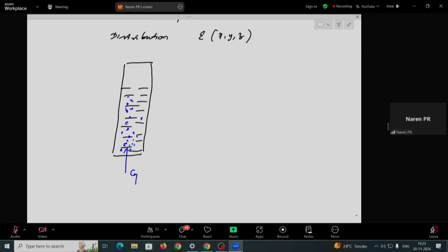Now, this could be like this. If you clearly look into this cross section, it is not everywhere that the gas is there. Gas is there in this region more, whereas it is very less in the other region. So this is what is called the distribution of the holdup in a particular column or in a particular reactor.